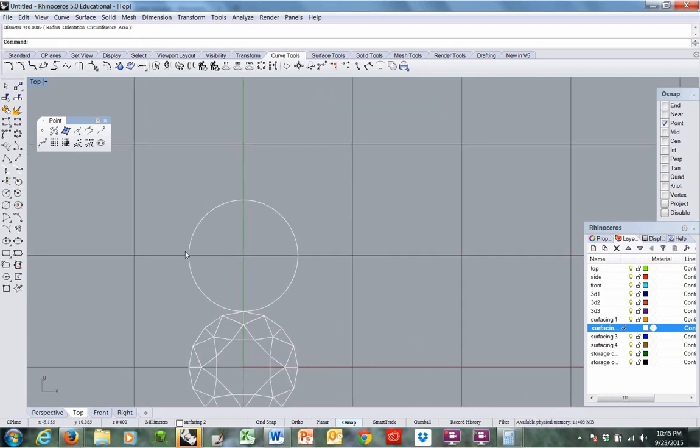And I need to be able to divide this distance in half. Okay? So I need to create reference geometry again. I'll do a circle diameter again, just to give us the practice. I need quad snap. I'll just left click it. I'll leave quad and point active at the same time for a minute.